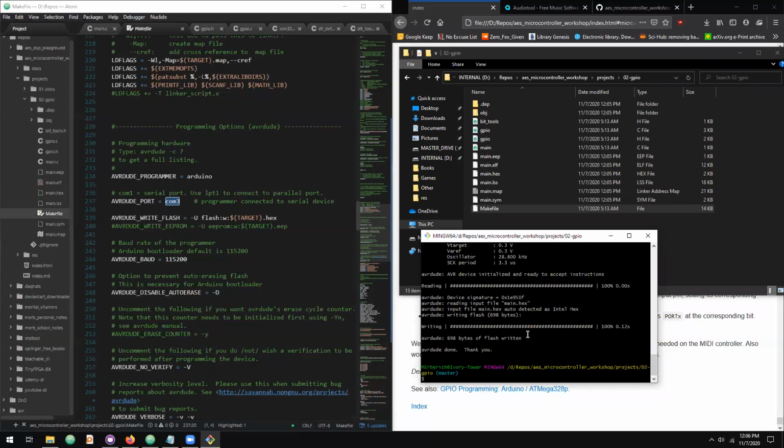Our device gets programmed, and now we can test this by, again, connecting our jumper cable from the VCC labeled pin, or I think Arduino calls it 5V. So that's our 5-volt pin, and that is equivalently a logic high. And we plug the other end of the jumper into pin 12. And we should immediately see the pin for the LED set the LED on. And if you want to turn the LED back off, just connect to the ground pin.